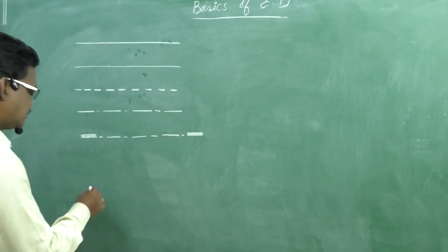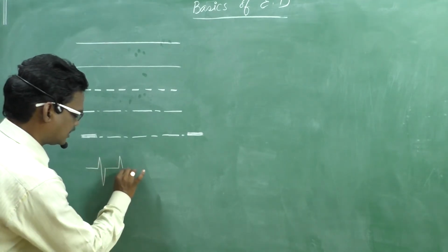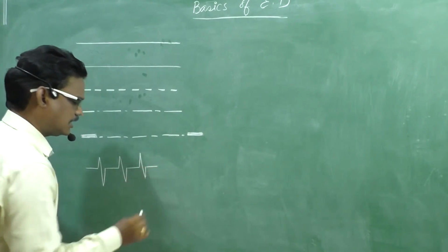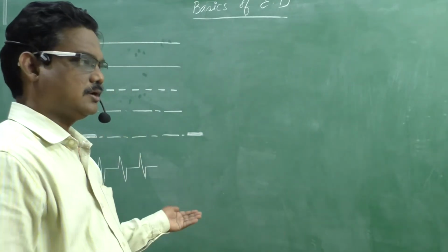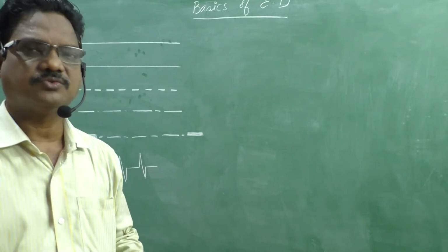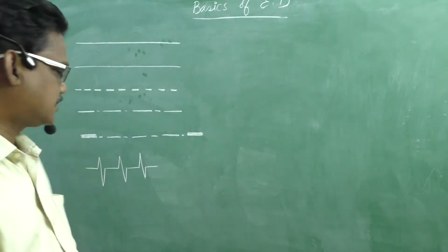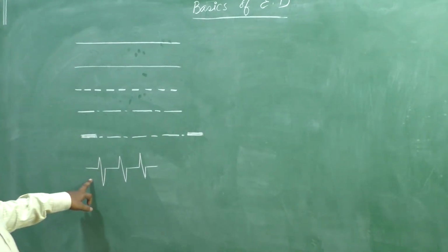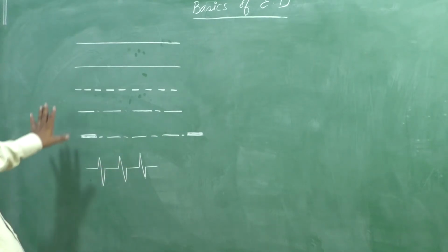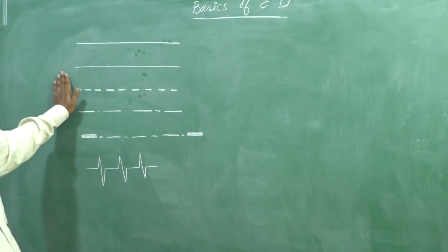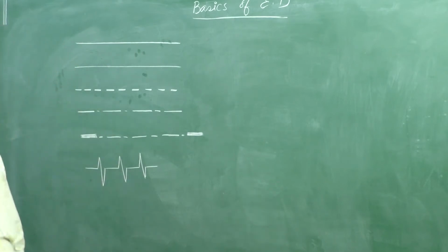Okay, next one is called a zigzag line. A lengthy object is there. The lengthy object we cannot draw on the drawing sheet fully. The details which we require, that portion only is represented on the drawing sheet. In such cases, to show the continuity of the object, this zigzag line is used. For engineering drawing purposes, these lines are enough. That is the reason I will close these types of lines here only.